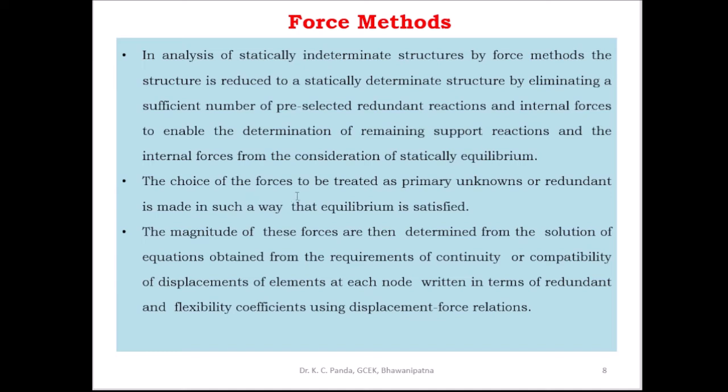The choice of the forces to be treated as primary unknowns or redundants is made in such a way that equilibrium is satisfied. The magnitudes of these forces are then determined from the solution of equations obtained from the requirements of continuity or compatibility of displacements of elements at each node, written in terms of redundants and flexibility coefficients using displacement force relations.